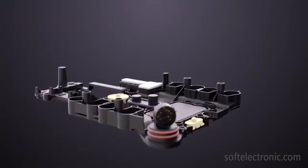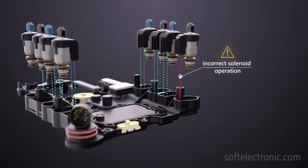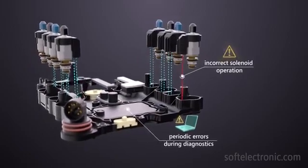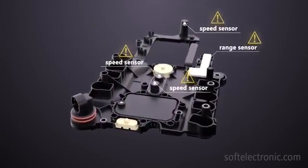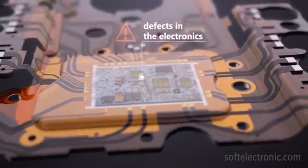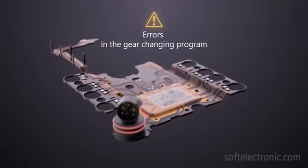The most common defects occurring in the control unit are: the computer control of the solenoids may be incorrect, and during diagnostics, various error codes may periodically be stored as regards their work. One or more sensors can get faulty, or the data from them may be implausible. Electronic components on the main board may be damaged. Errors can appear in the software program of the gear change control due to incorrect data.